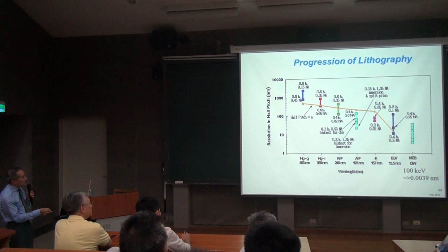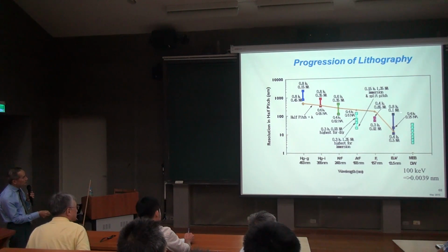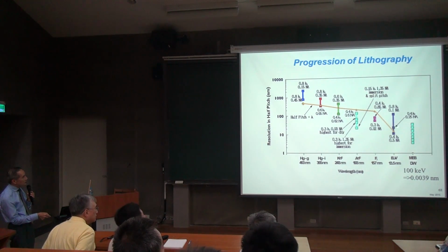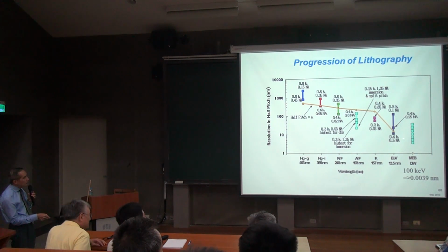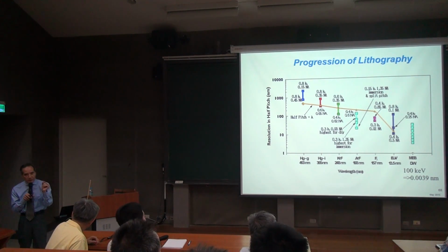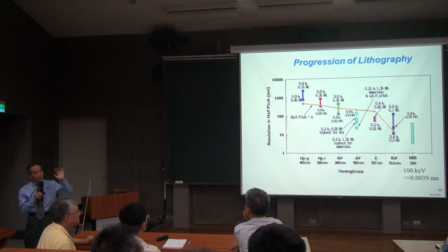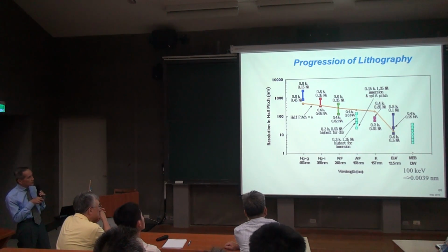Okay, now EUV. EUV was supposed to take care of 100 nanometer, but it didn't happen, at a very relaxed NA and very high K1. We're hoping that it will enter here. It didn't happen. Now we're hoping that it will happen here. If it doesn't... now notice we didn't put 0.3 K1 here. We put 0.4 because with EUV the wavelength is short. The straight line and other things are more difficult. It's much more difficult to get a smooth surface because the wavelength is much shorter. So it probably would end at 0.4 K1 instead of 0.3.